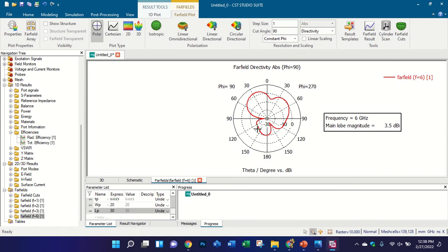And this is the back lobe. In an antenna case there should be no back lobe. There should be a main lobe that may be wider, or the pattern can be a circle. If you have a circular pattern, then it can be called an omnidirectional pattern, meaning your antenna is working in every plane, at every angle. But if you have a directional pattern, then it must be on the upside, like this, and there should be no back lobe.